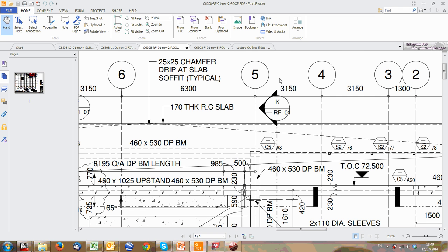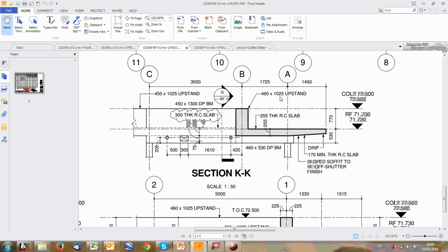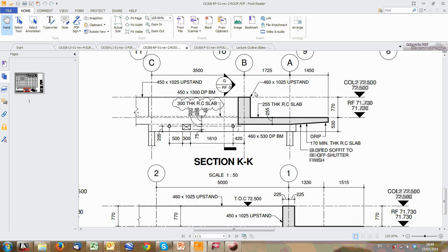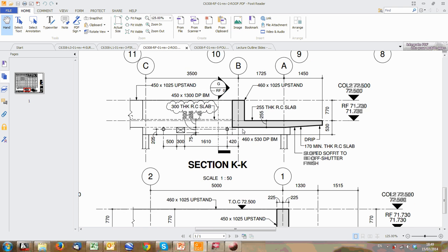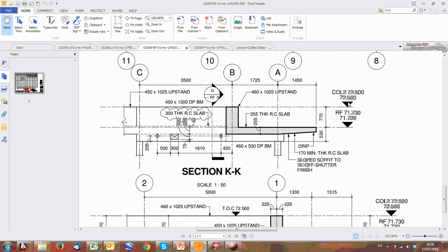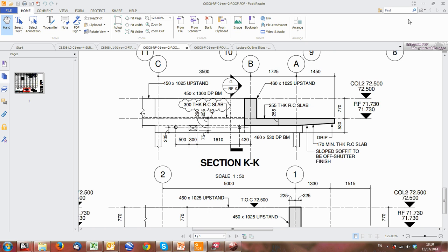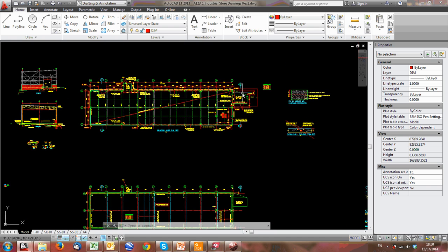You'd need to make sure that wherever you put the section, it's K, and it's on roof RF01, and then you can go to RF01 and find all these details. So you tell them on the drawing where to find the section, what the section is, and then you go to the section and it's got information that might not be immediately clear on your drawing. You can put layers there, levels there.